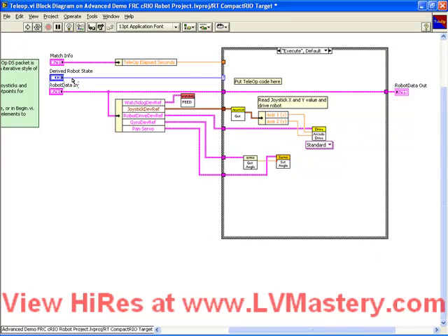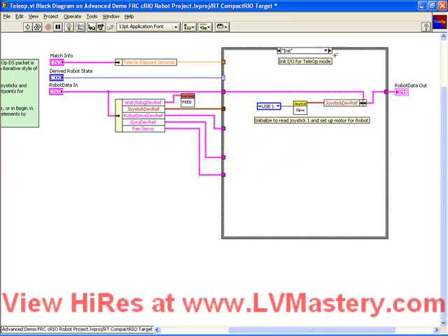Remember that in the Robot Main.vi, we have a block which is determining what state the robot's in, and that's feeding that in to this sub-VI. In normal operation, it's going to be sent the execute command, and that's why we put our teleop code here. But the very first time it runs in teleop mode, whether you're switching back and forth or just the very first time, it's going to be running in init. In the init state, the joystick reference is being opened.